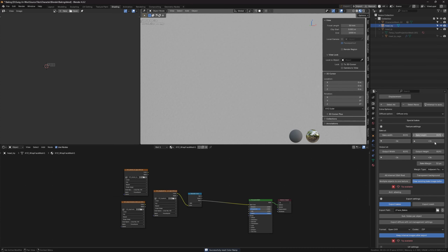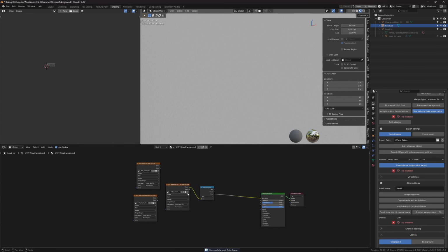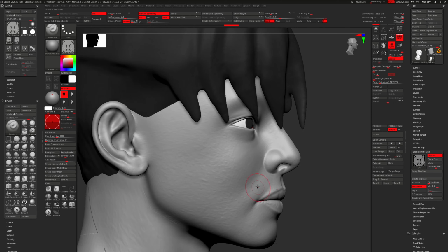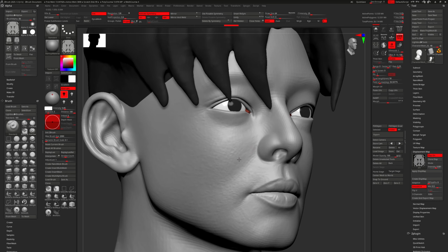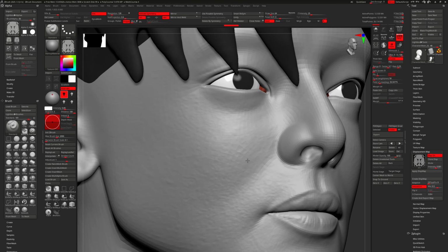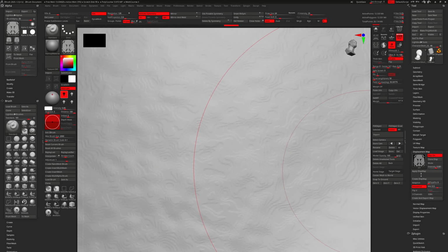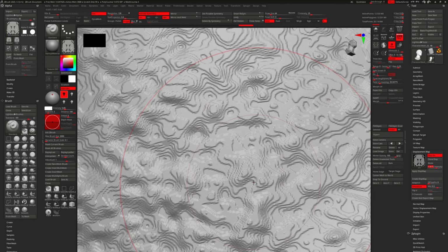And another thing I found is that while I'm baking it in Blender as an EXR, I get stepping issues. Okay, just quickly show what I mean. So I imported the TextureXYZ map which I baked on top of my model, and if I zoom in, can you guys see the stepping? Okay, I'll just increase the intensity.